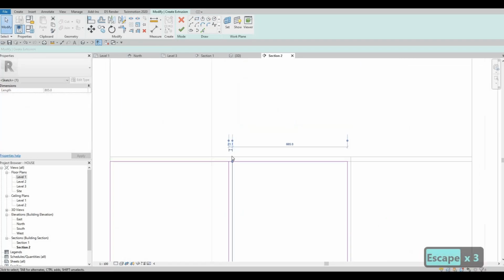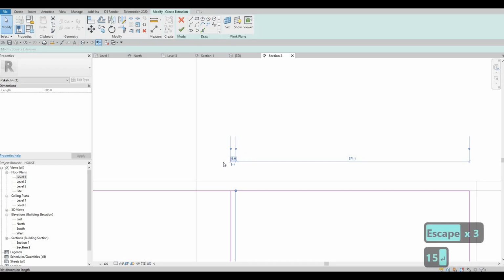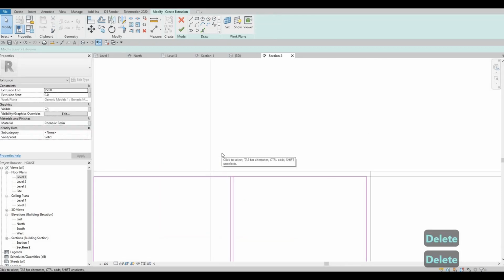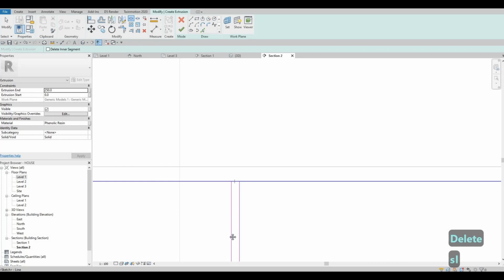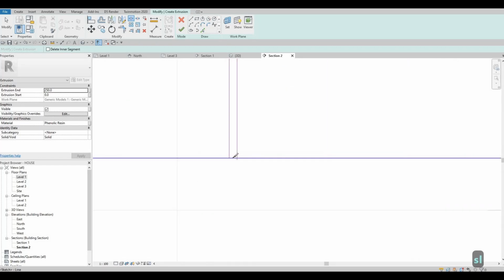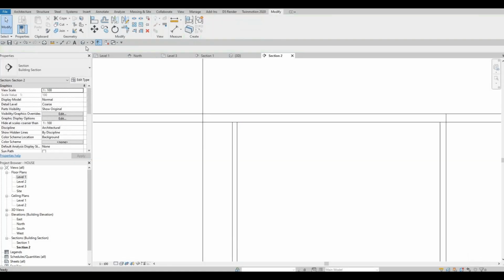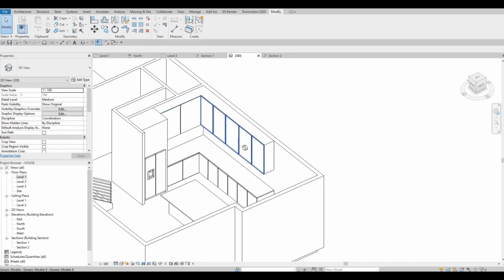And then make sure the thickness here is only 15, and then delete the small lines that we created. SL, split element here, and then TR to trim. Extrusion, we set it to 20. Click finish and finish, and let's look at it.